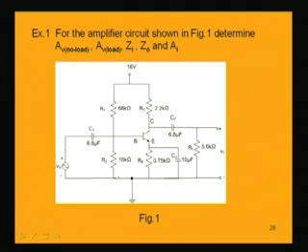In order to solve this circuit, no load means that whenever you have 0 load here, the load RL is not there, and we will have the no load voltage. Whenever you apply the load RL, whatever voltage is available will be the load voltage, and there is a difference. When RL comes into the picture, RL also has to be included, and that changes the voltage gain, and the loaded voltage gain will be less than the no load voltage gain.